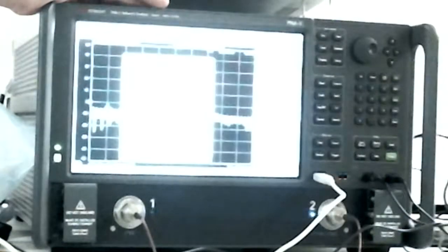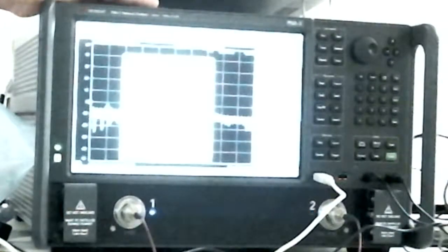It exists in ADS. It's just like if you said your device is not 50 ohms, then how do you terminate it, right? Every single port is going to have a different termination. You need to make really good terminations to make sure you minimize the reflections. It becomes really, really complicated. If your device is 50 ohms, you can just buy really good 50 ohm terminations and then not have to worry about it. Yeah, so that I think gives you a pretty good idea of this.